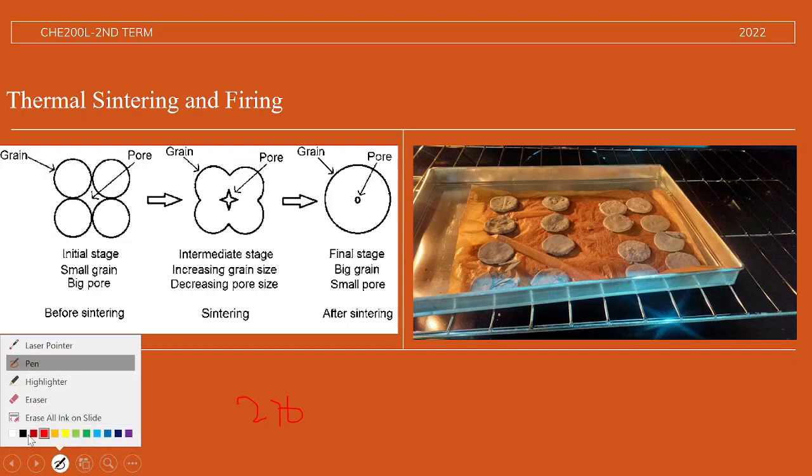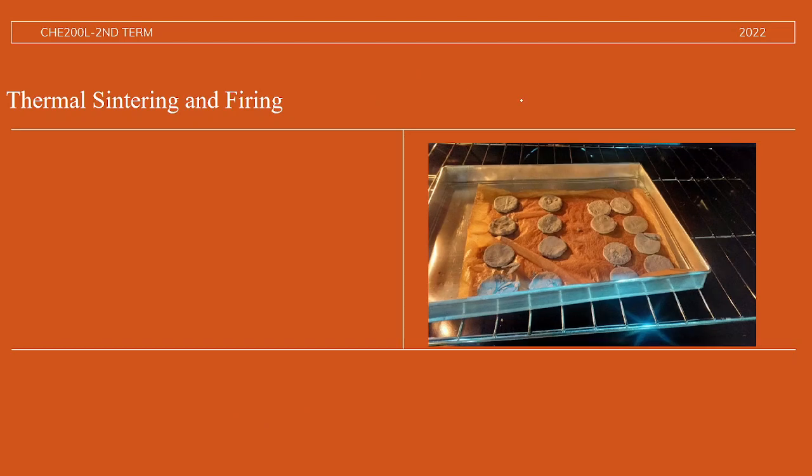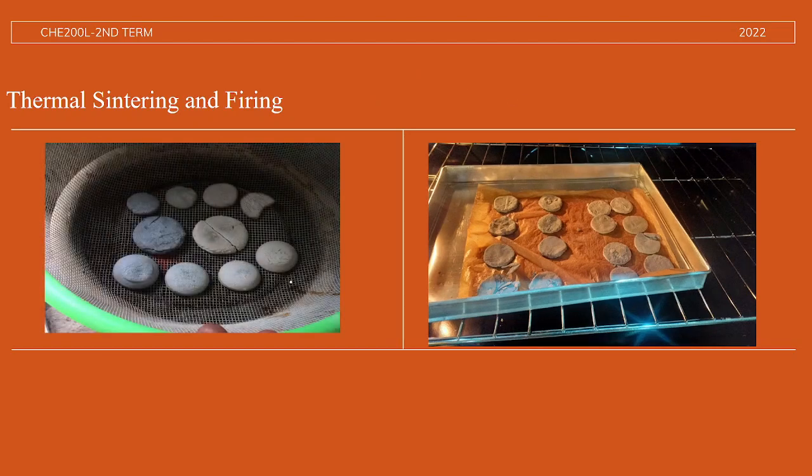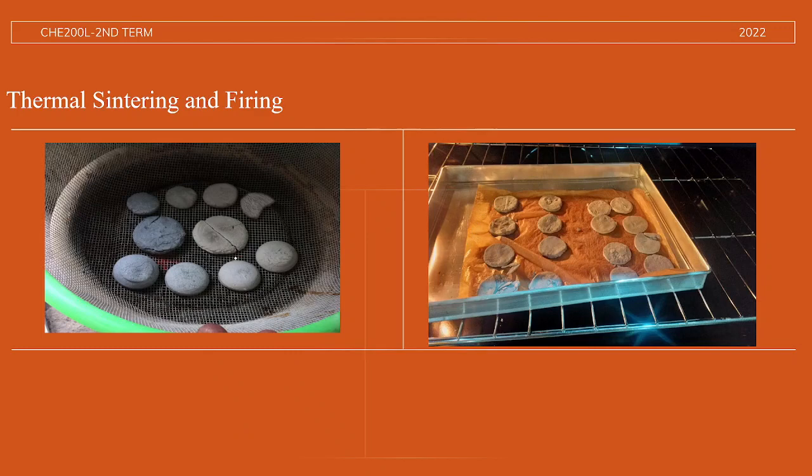We would start at the bottom, which is 50 degrees Celsius, and continuously increase that every 2 minutes in an oven. This is direct firing, but we also do this for the membranes that cracked. We repeat that with the same thickness and the same sizes.